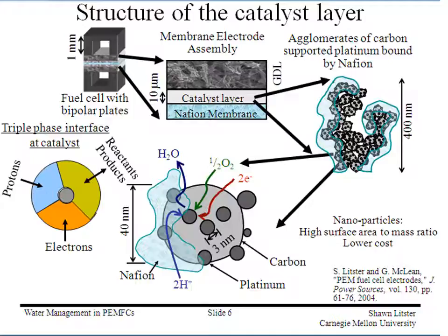Once you get to around 30% of it being filled with carbon, you'll be able to conduct electrons through the whole thing. It's a very non-linear percolation. If you have 10%, you have almost no electrical conduction. 15%, almost none, and then you get into 20 to 30, and it just starts rising really rapidly.